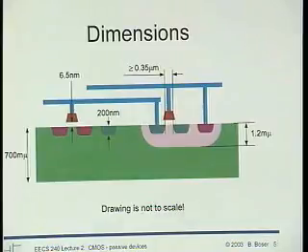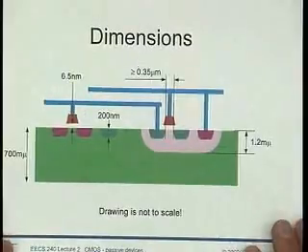But once you go to deep submicron technology, it doesn't add any extra accuracy to our model. So we do something that gives us the information we want without fussing with LD. So we have one device length, and we know that physically, in the transistor, some more complicated stuff can be happening. So we just have the drawn length, the one that the layout person knows to make his mask from. That's our channel length. No other ones.